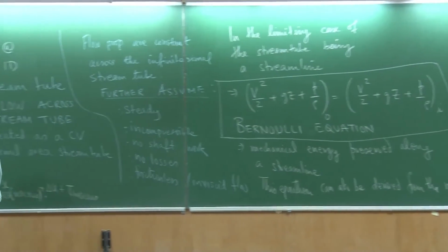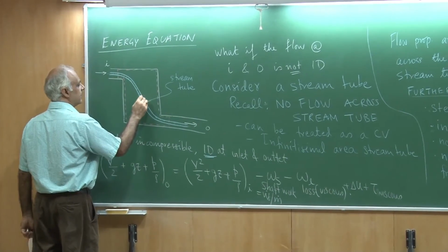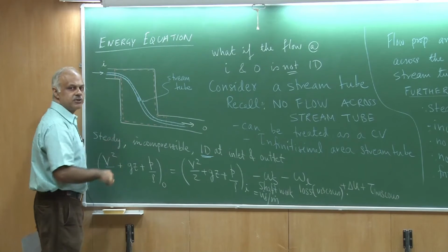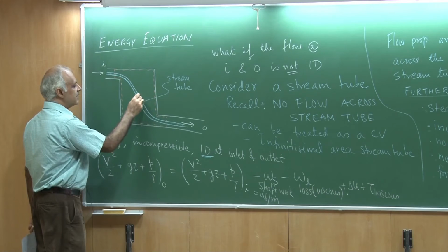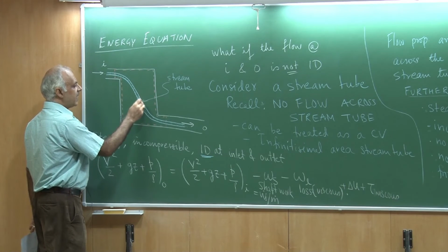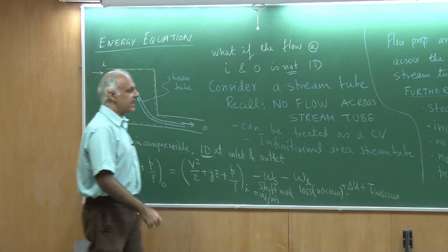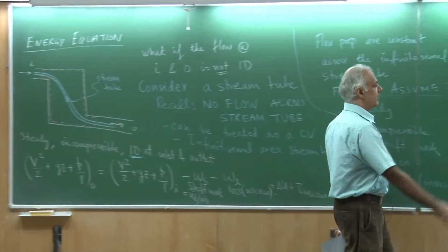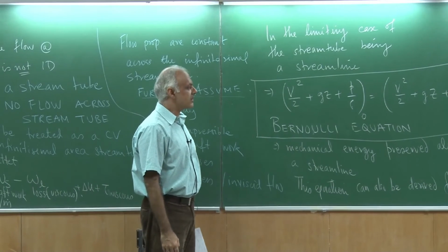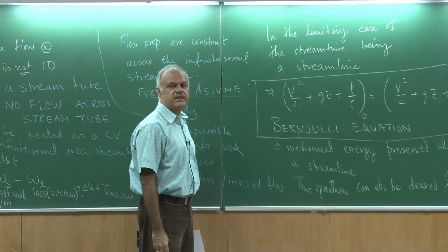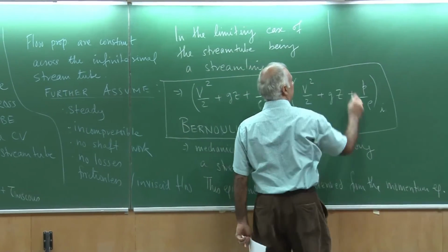So as a fluid element moves along the stream tube, along the streamline, it has to do certain work against the pressure. So there is a pressure acting on it upstream and downstream, and that appears as this term. So, this is the additional term that you would get in fluid mechanics, which you do not see in dynamics of projectiles without air resistance. Good.